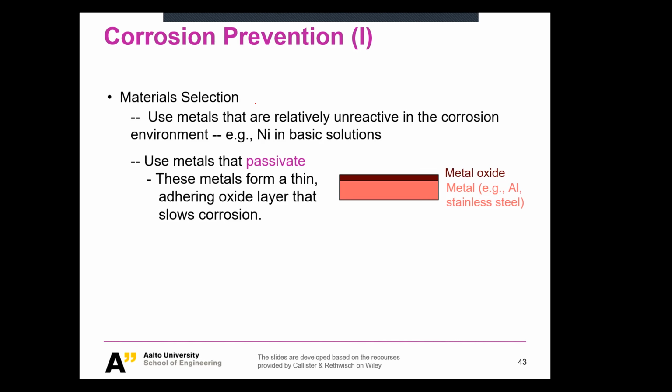If you have to choose a material which is going through some acid situation, you first could choose those very noble ones, but they're also expensive. The second one is more engineering relevant: you go with metals with passivation features, which is why we developed aluminum alloys and stainless steels.